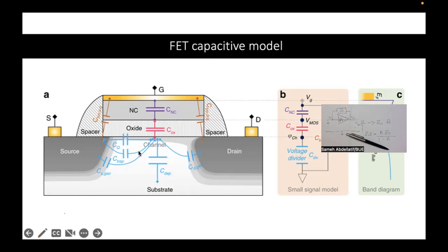This can be controlled, for example, when we consider the C oxide, or the oxide capacitance. Having a thick oxide layer reduces the value of the C oxide, which is some sort of an added value for your circuits. However, as you definitely know, nowadays we are going toward low dimensional transistors.